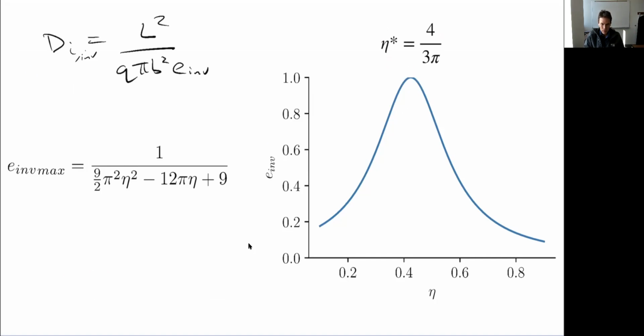So we've got this tension here where I'd like, from an aerodynamic perspective, to keep my center of lift somewhere over here. But from a structure perspective, I want my center of lift to be as far to the left as possible.